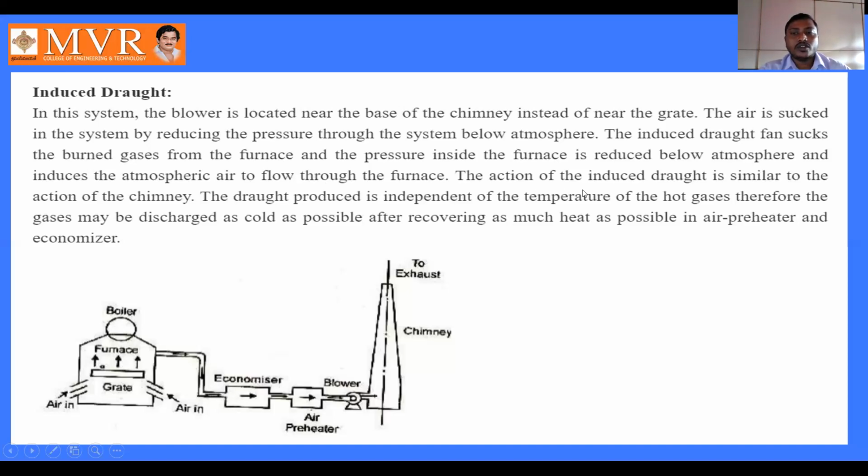The action of the induced draft is similar to the action of the chimney. The draft produced is independent of the temperature of the hot gases. Therefore, gases may be discharged as cold as possible after recovering as much heat as possible in preheaters and economizers. This is what the induced draft is about.